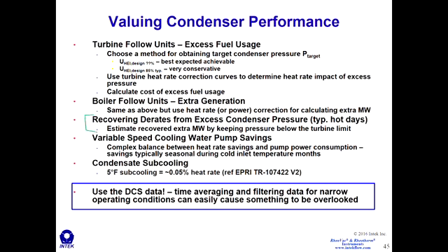Then there's recovering derates from excess condenser pressure. So typically on hot days in the summertime, if you can estimate your recovered megawatts by keeping the condenser pressure below the turbine limit, that's another way to value condenser performance.